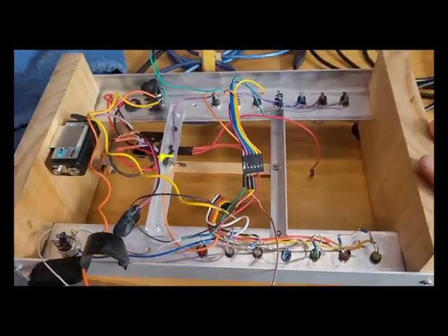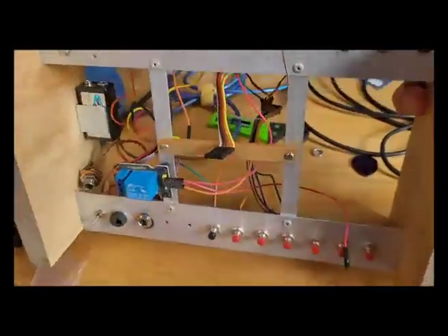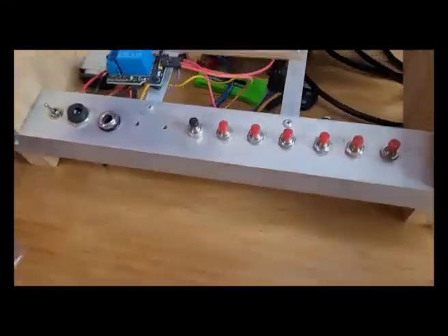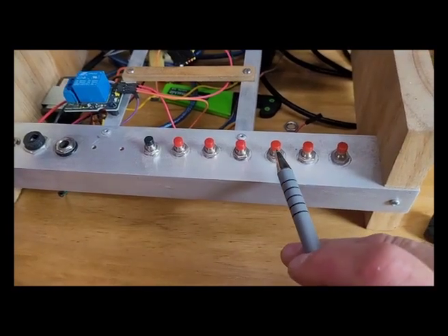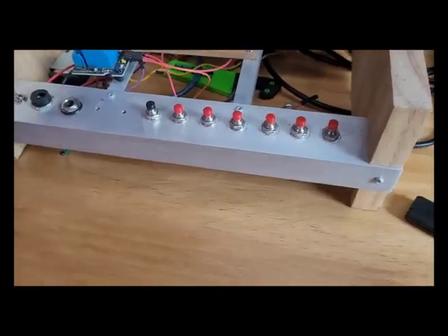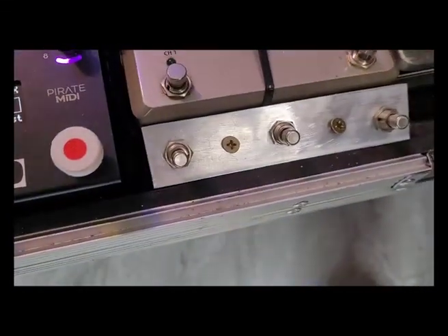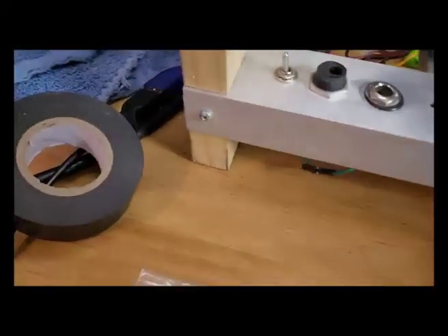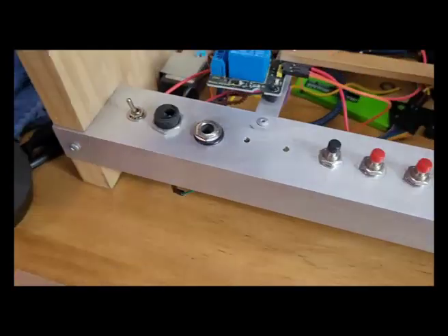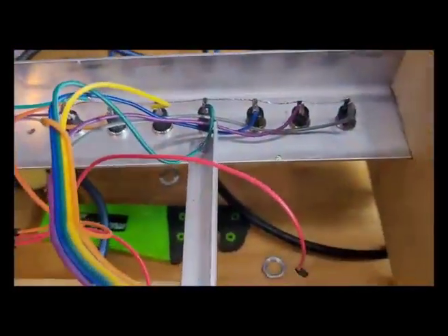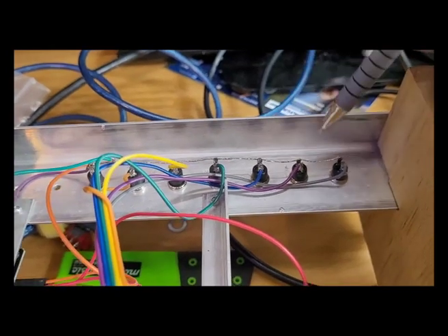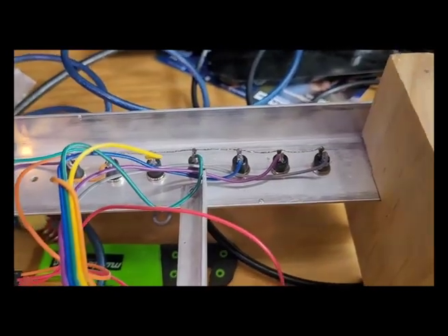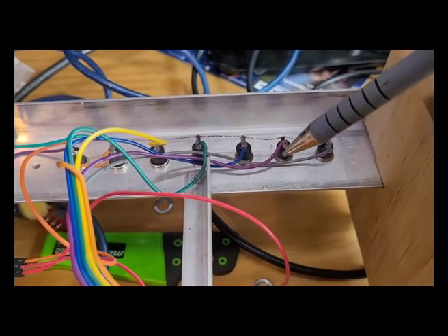This is a test bed I use for all sorts of little projects, and it just has some hardware mounted on it. Today we'll be using these 3 switches. These are single pole, single throw momentary switches. They're just smaller versions of the switches on the pedal board, and this TRS socket. Turning it over, these are the 3 switches we're talking about. We'll call this one tip and this one ring, and this one in the middle will be tip and ring connected together. So it's grey, purple and blue wires.